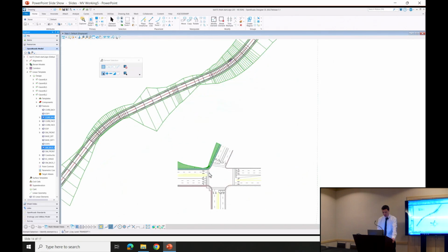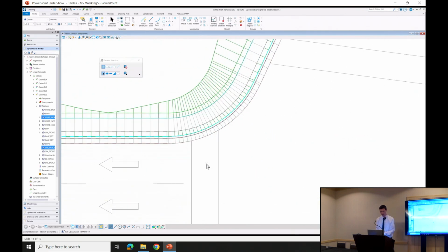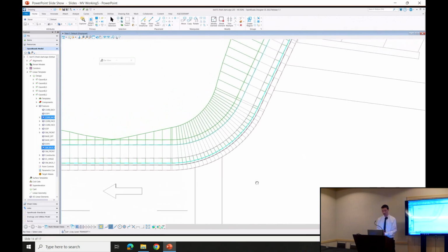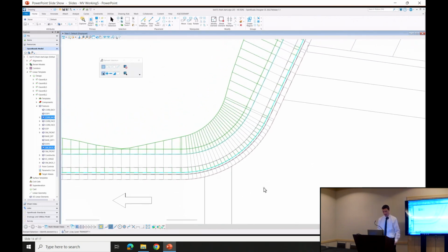And this is what you'll typically find for the line work representing the design for the sidewalk area of an intersection. It is something that can be reproduced in any form of the CAD environment, such as OpenRoads Designer or Civil 3D. Often the starting point of this proposed line work is limited to a collection of survey points from the field, and getting this information interpolated to help form a flow line, curb and gutter, and the back of the sidewalk that is as close to reality as possible. I currently have those highlighted in the cyan color, and you can see here I'm able to isolate it.